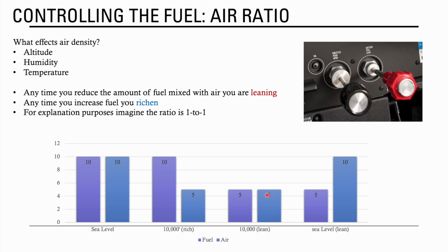Could you fire back up though in the air? Like if it was too lean and the engine shut off on you? Oh, yeah. Usually the prop, if you shut it off, it will continue windmilling, meaning the prop is still spinning because of the airflow. And if you put the mixture back in, it should just start back up. So I've had students accidentally shut off the engine before, and you just push it back in. If it doesn't come back on, just get ready to land.